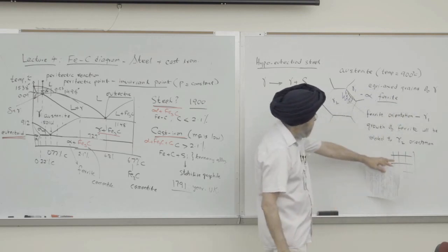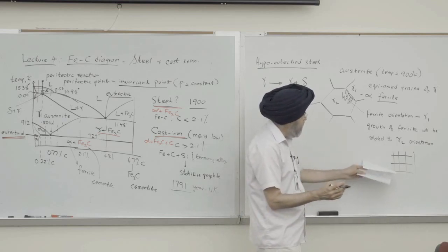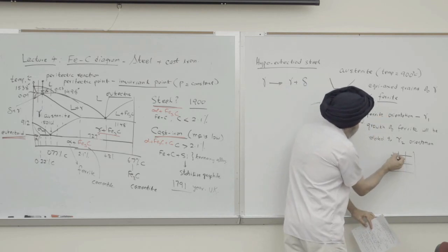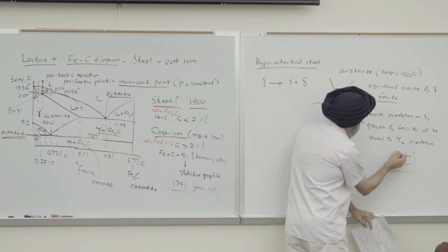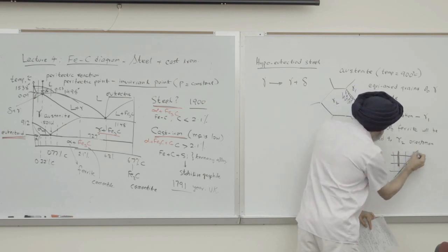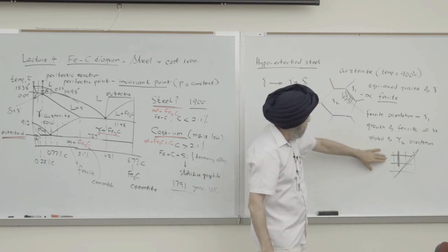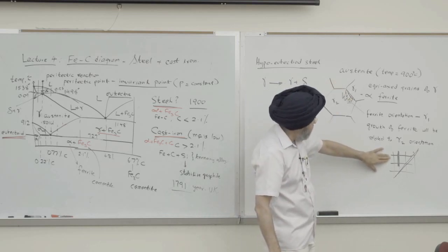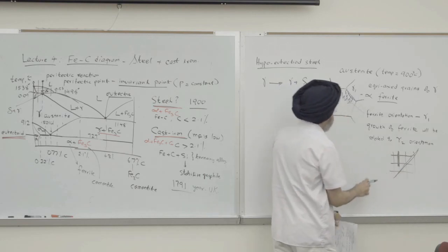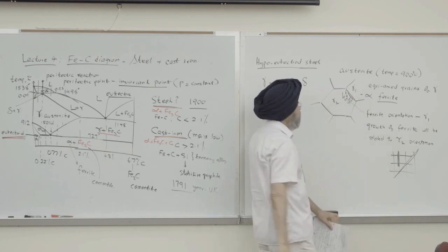I've just drawn in 2 planes, but in 3 dimensions, it's cubic. Then this ferrite could grow along this direction, or it can go along this direction, etc. In other words, the ferrite growing into gamma 2 has a crystallographic orientation to gamma 2 in terms of the direction it grows, but its actual orientation is in sync with gamma 1.